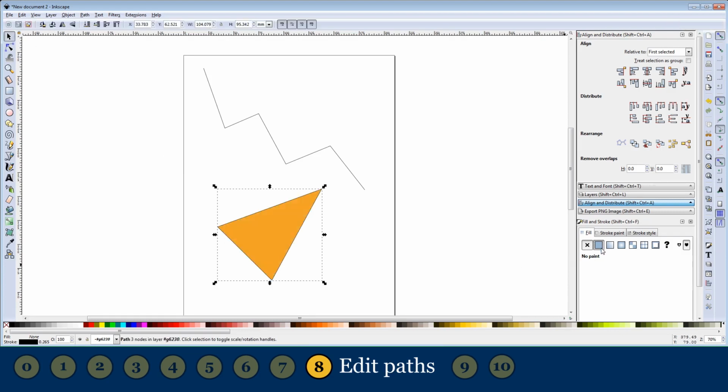Of course, you can select these shapes and tweak their fill and stroke. But that's not all. The Bezier pen's real strength is in making curves. If you click on an anchor point and drag the cursor, you'll see a set of handles grow out of the anchor point. The length and orientation help shape the path you're drawing, allowing you to make very detailed tweaks.